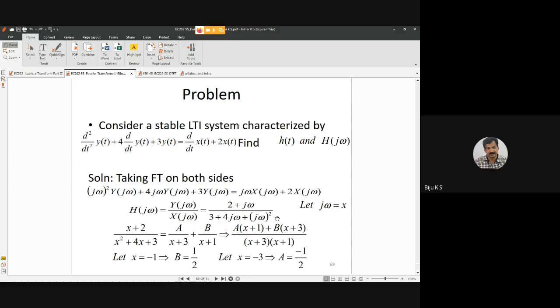So numerator and denominator we can get, and substitute different values. Omega equal to 0 first, so that I can know it is equal to 4 by 9 maybe when omega is equal to 0, and then higher values of omega, so that I can plot the magnitude of H(j omega) versus omega.